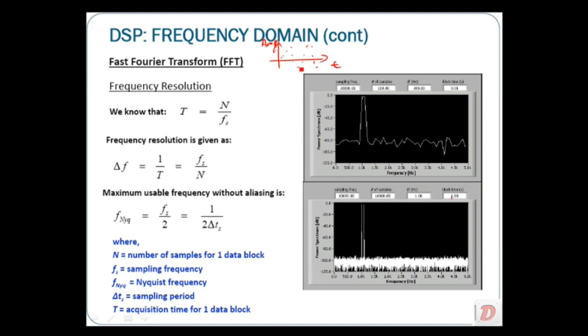The x-axis, how good your delta t is, the resolution in time, is defined by your sampling frequency, fs or SR, sampling rate. If you have a very good sampling frequency, you get a very good delta t. If you have very high bits or amplitude resolution, you have very good quantization on the y-axis. Then you can analyze your digital signal very well if you can analyze in time domain.